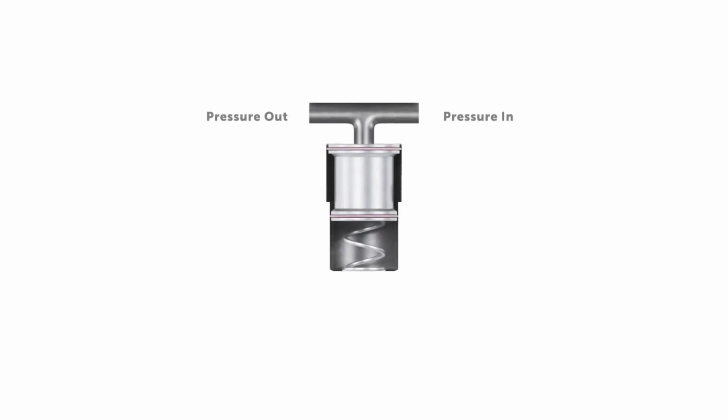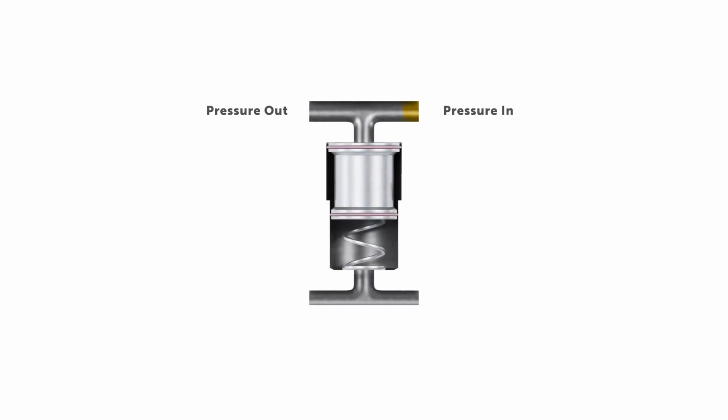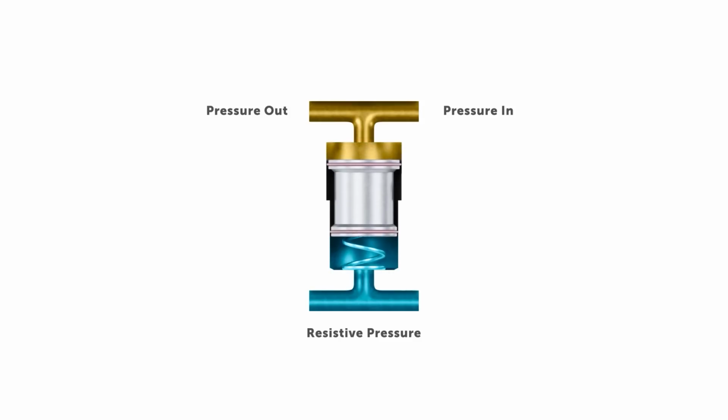In addition to the level of mechanical control the accumulator provides, some transmissions have additional solenoids that can deliver fluid into the chamber on the backside of the accumulator valve, causing additional resistance to accumulator motion. The more fluid on the backside of the accumulator, the more pressure bound for the clutch piston is needed before the accumulator will move and bleed clutch pressure off.